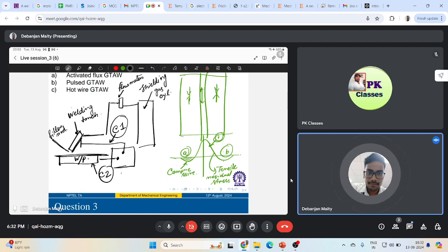Now over here, this allows both the welding current from the power source to enter the electrode and the electrode to be cooled to prevent overheating, as it is connected to the copper cable or copper contact tube, as I was saying. The workpiece is connected to the other terminal of the power source through a different cable.